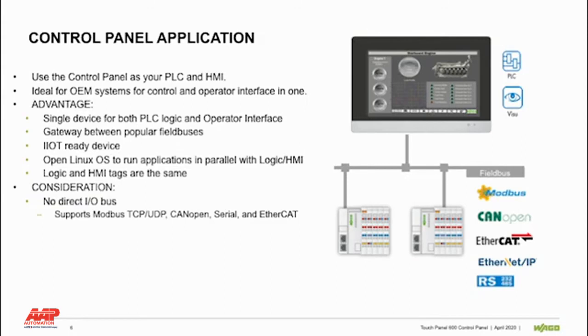So when using a control panel, you need to consider that there is no local bus, so you can use one of the supported fieldbuses to connect to distributed I/O. And I would also note that via fieldbus you can exchange data with Wago and third-party PLCs.